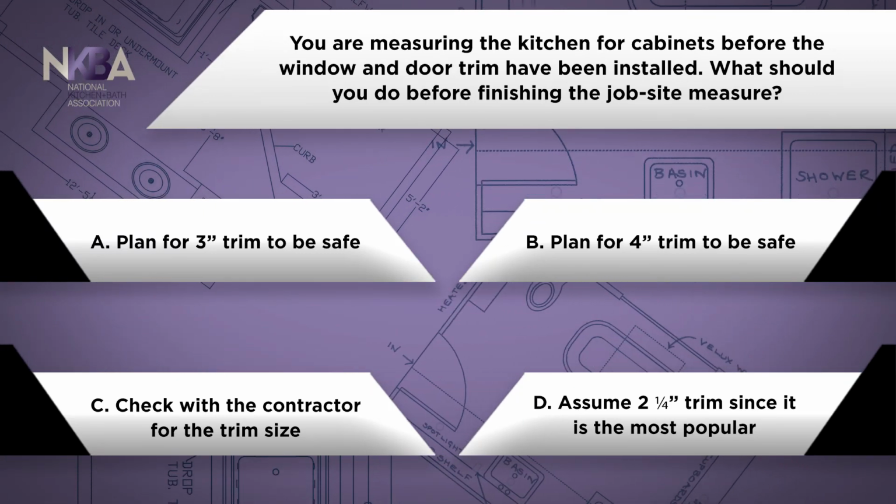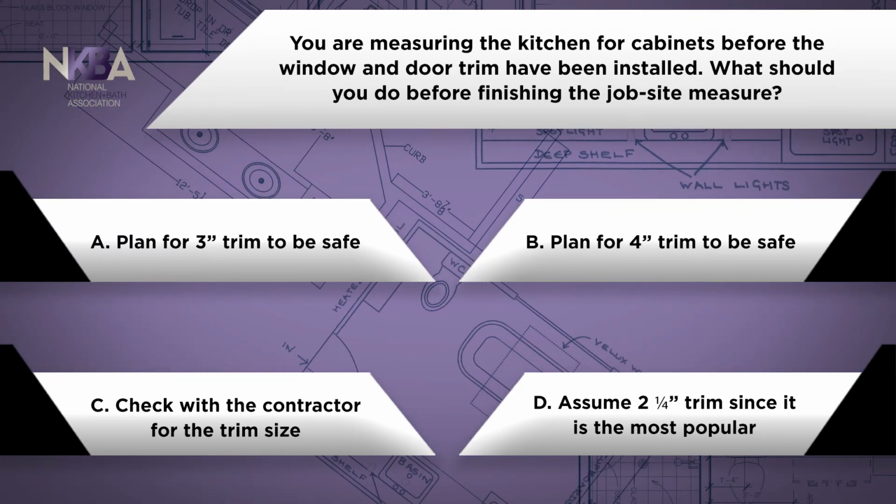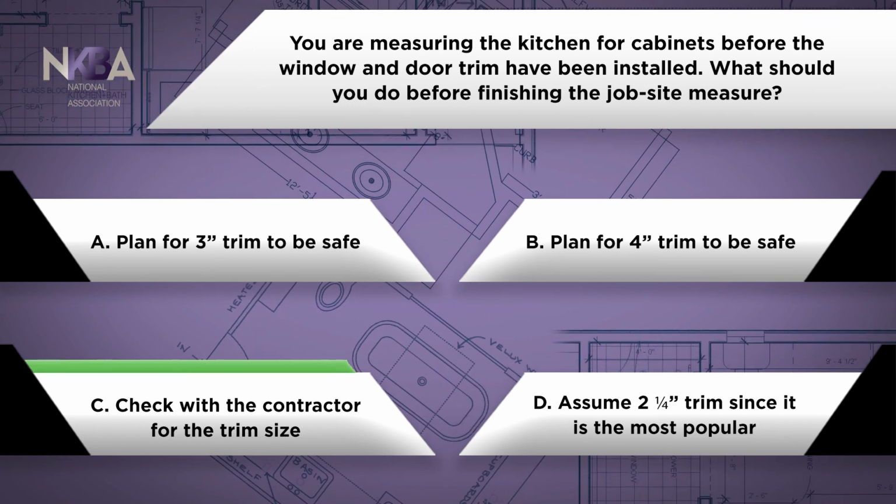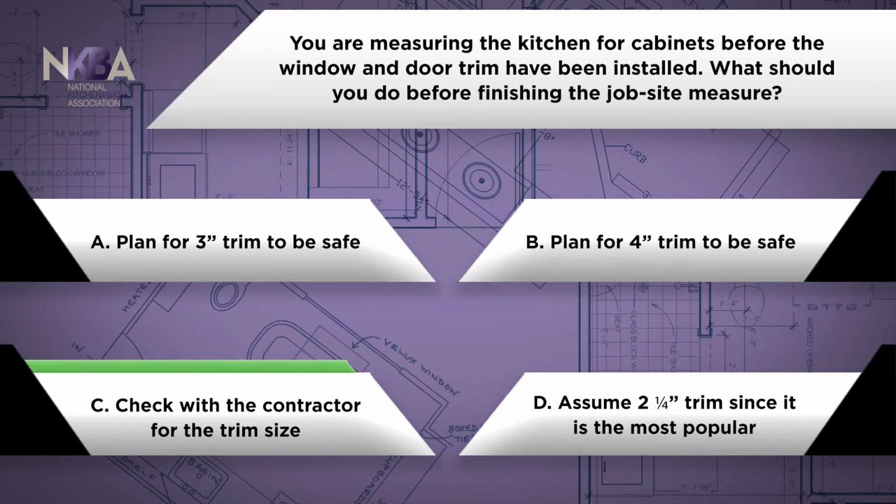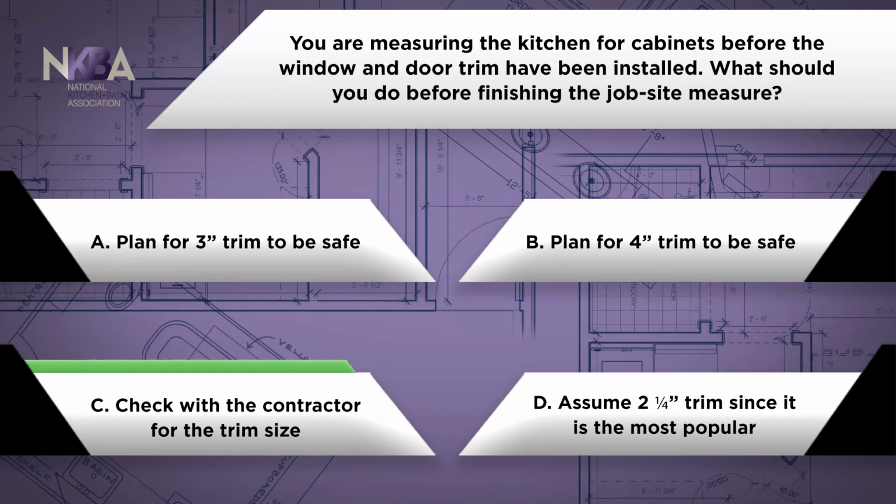The answer is C. Never assume, always check with the contractor for trim size before finishing the job site measure.